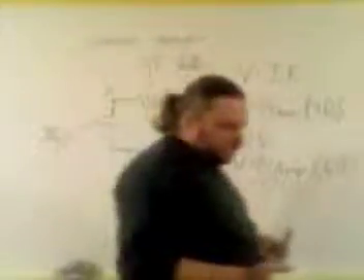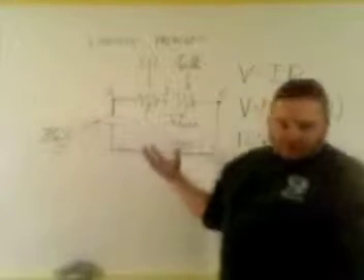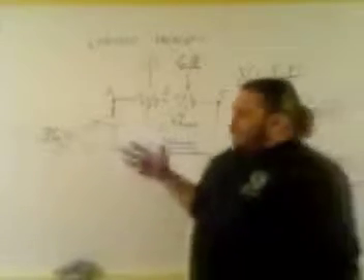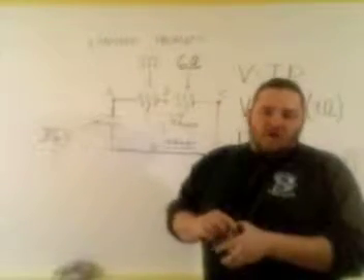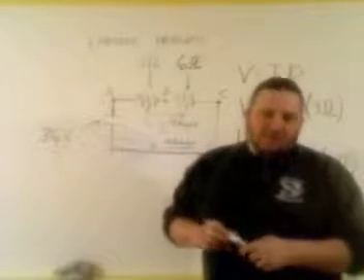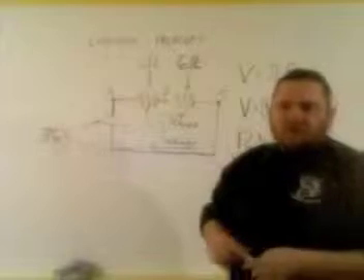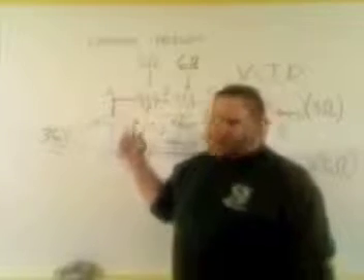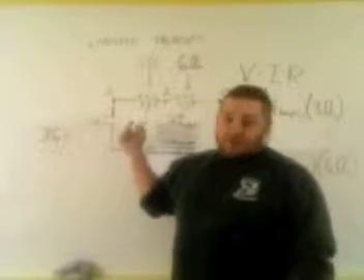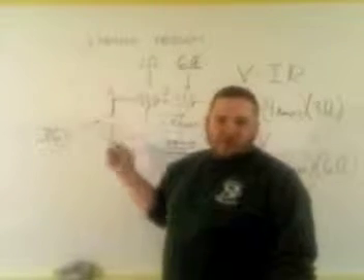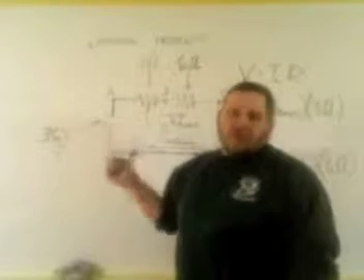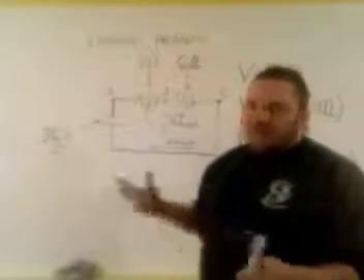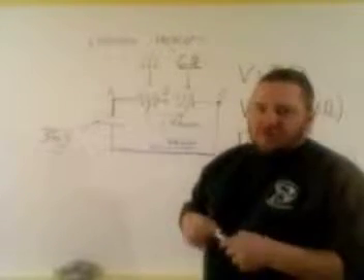On the flip side, if you think about building something and you're plugging in a power supply that's not supposed to go into that component, you take a 120 and you plug it into a flashlight that's only supposed to be taking 6. Okay? What ends up happening is that the resistor in that flashlight, aka the light bulb, has to burn off 120 when it was originally built to only handle 10. So the problem with doing something like that is that you're burning off that tremendous amount of potential in something that's really not designed to do that. That's why your light bulbs burn out really, really quick in that sort of situation.